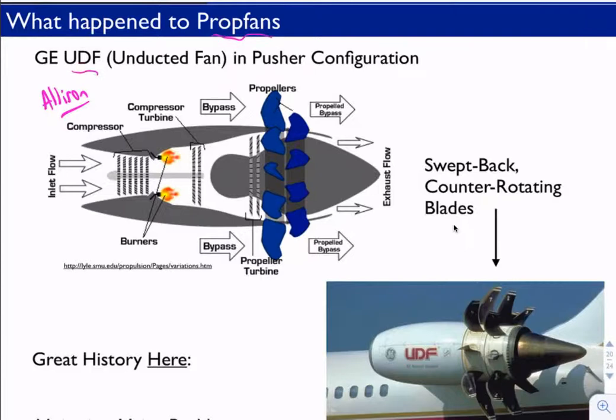And you can see this looks similar to a turbojet where you have a compression stage here. You have your combustion stage here. You have your turbines here. Turbines only driving the compressors. So far it's basically a turbojet. But then you have these hot gases here passing through the second section here, and these fans here are used to extract energy from that flow to drive these external props.